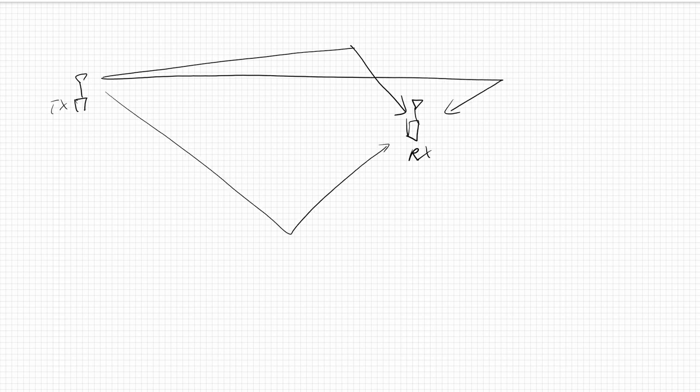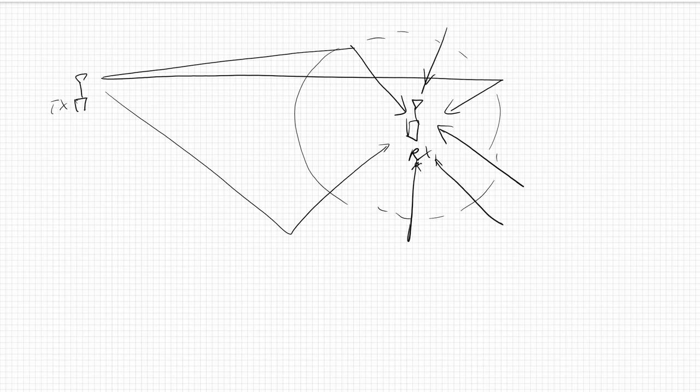And the model here for me at the receiver is that I assume that the paths are incoming all over, within the direction from 0 to 360 degrees. It's just coming everywhere. And with all these incoming paths, they have the same distribution in this angle. Also, they have the same distribution of the amplitude of each path. So this is called the Rayleigh fading model.